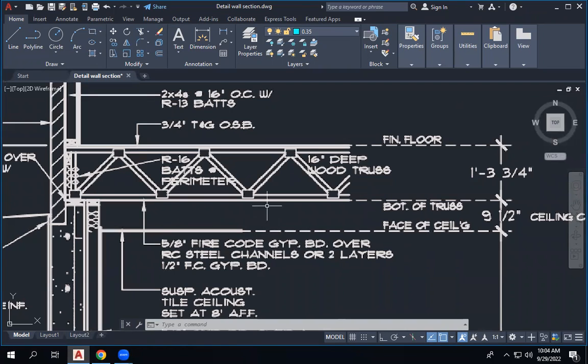It depends. If you have this one exposed and you need to tell the structural engineer, I want the look like this, then you give a detail and he will tell you the necessary sizes. That's how it happens. If this one will be closed and no one can see the truss because we have a ceiling here, then there is no need to give any details for this one, just draw it as it is. If the engineer wants vertical, it's very cheap and you can do it in smaller sections. It's okay because you put a ceiling and close it off.